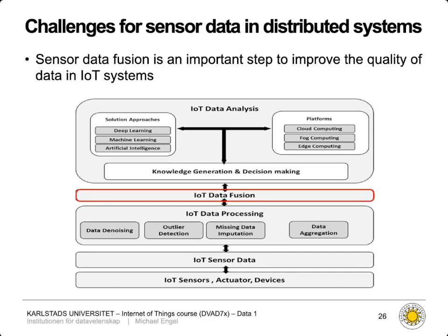We might apply an ultrasonic sensor to measure a distance and also a 3D camera or a LiDAR. If we combine these data, we can have a better precision because an ultrasonic sensor measures at different frequencies, so this might not be reflected by something that a laser from a LiDAR might be reflected from, so you get better information.